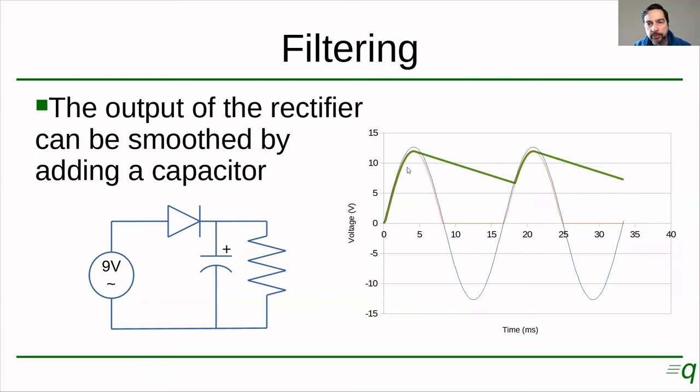Remember, in the previous circuit, the diode conducted all the way until the voltage was 0. But now, the capacitor is holding the voltage here. So this reached 11.8 or so volts, and then this one started to go down. So the diode is in reverse, like I said, and not allowing the capacitor to discharge to this side. So the capacitor discharges to this side, and it's going to discharge slowly if the capacitor and the resistor are sized correctly.